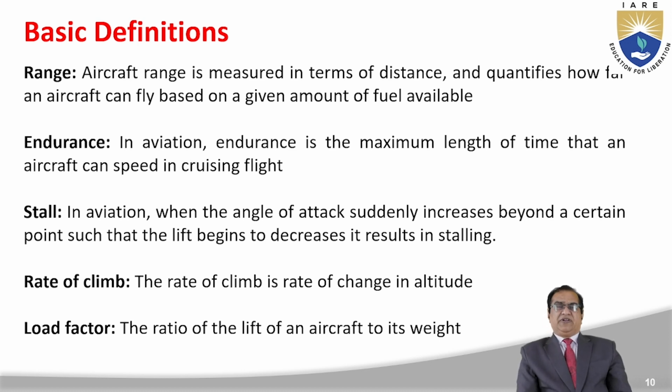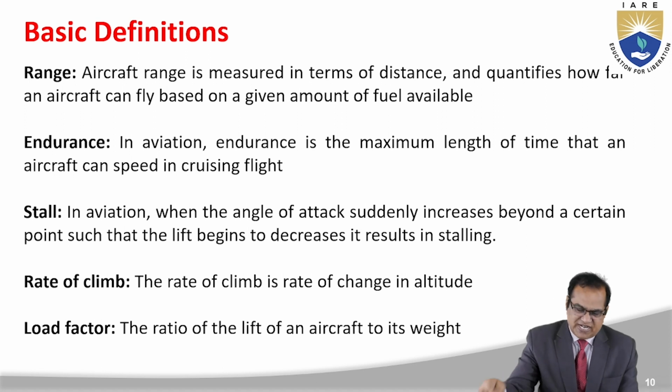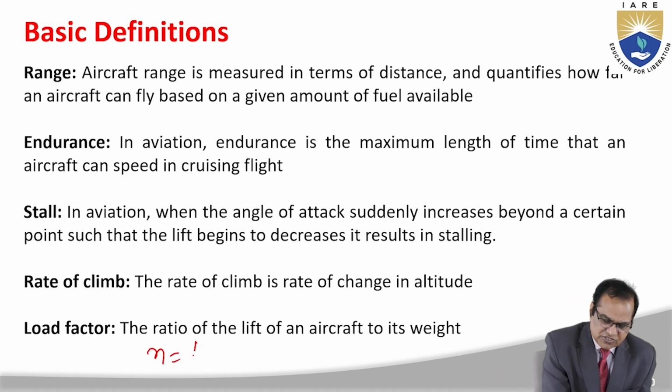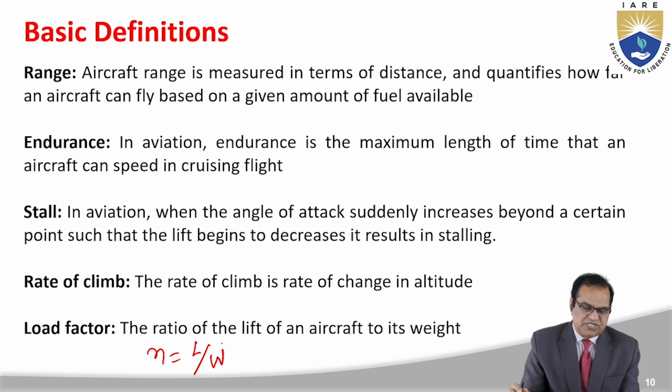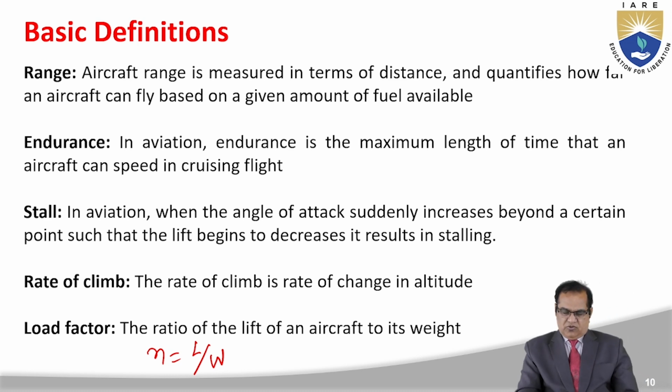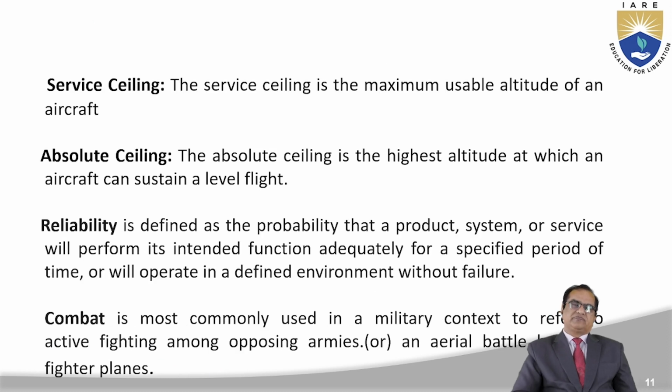Another term is load factor. It is the ratio of the lift of an aircraft to the weight of the aircraft. This load factor is designated as a small n, and this is lift by weight. So this is your load factor, a very important parameter for aircraft performance.